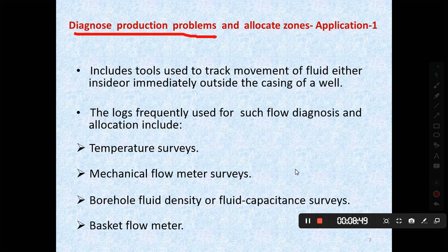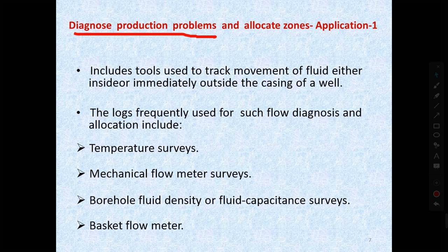It simply means that if your well is producing extra water, or extra gas, or if the oil production is reduced, or the gas production is reduced, especially related with the production, why is the water production rising? What kind of problem is it? Maybe water is coming through behind the cementing, or maybe oil is lost because of a blocked or plugged perforation. So what is the issue?